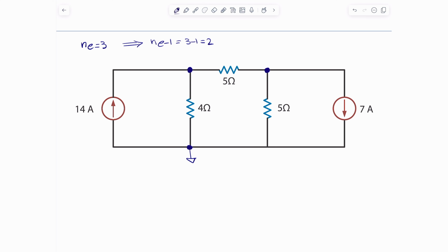In these 2 equations, I'll get a couple of voltages. For the first voltage, I'm going to assume that this is point A, so that will be VA. And this one here will be VB. That's the plus, and of course the minus is in here. So it gives me VA and VB, or actually we're going to write it so that we can compute VA and VB. If I know VA and VB, those are the node voltages. Sometimes nodal analysis is called node voltage analysis, because if I know the node voltages of these 2 points, I'll be able to figure out all the other voltages and the currents in the circuit.